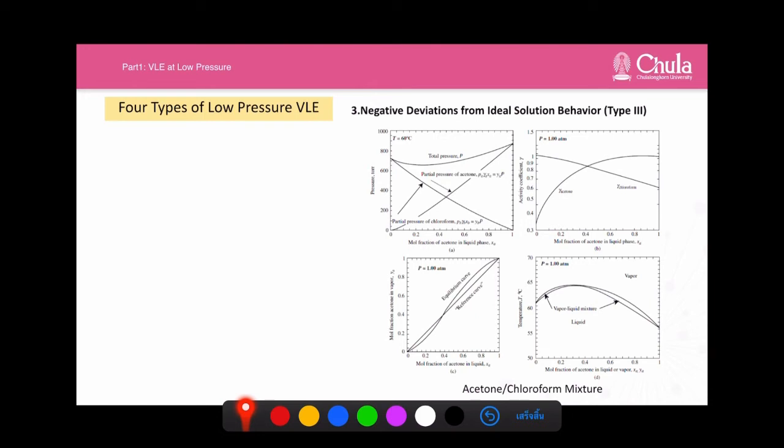And if we look at bubble point and dew point again, it forms a point somewhere here where the boiling point is at the same place as the dew point, okay, which is the behavior of pure component. But here you see that the azeotrope has the highest temperature, right?